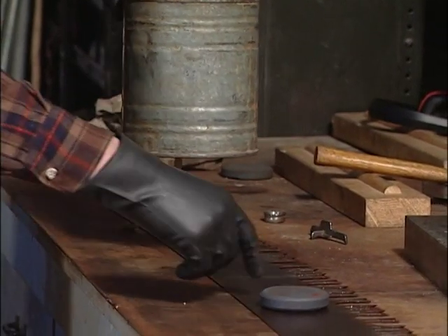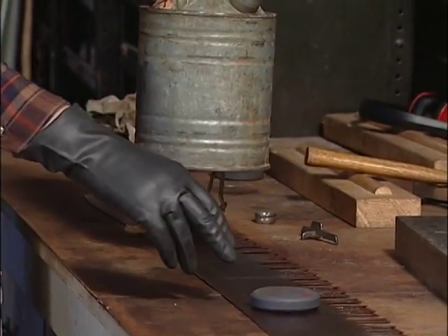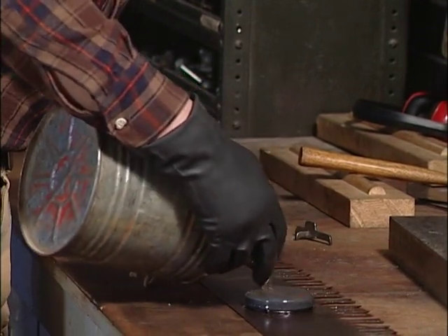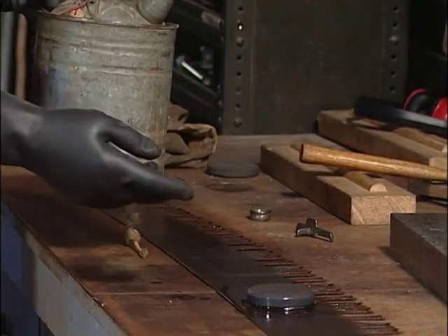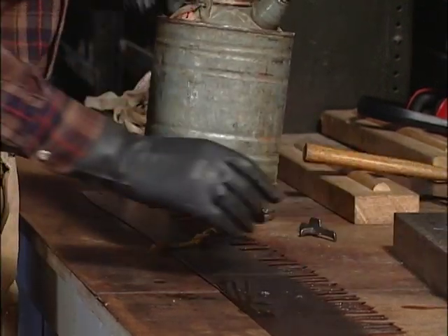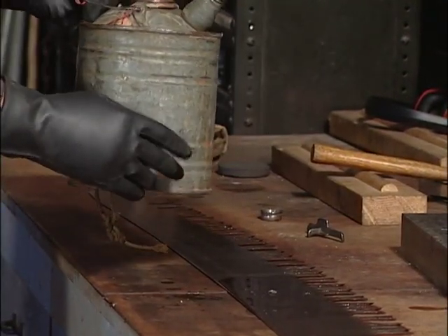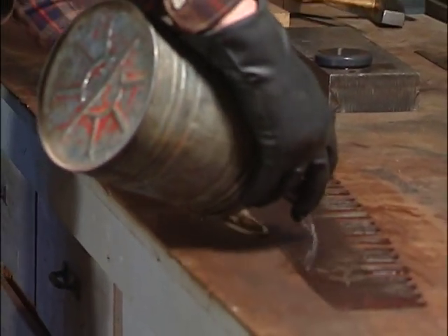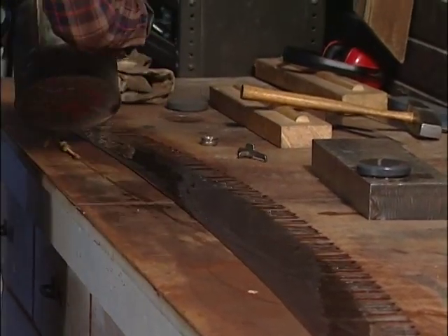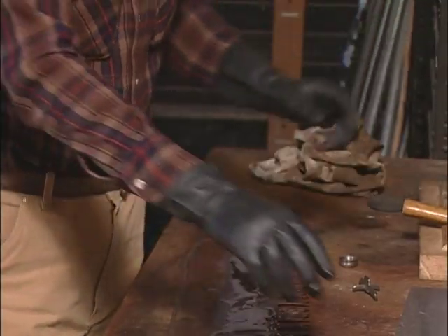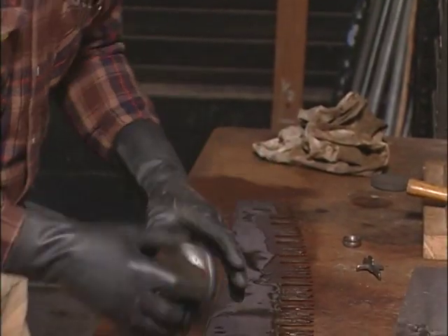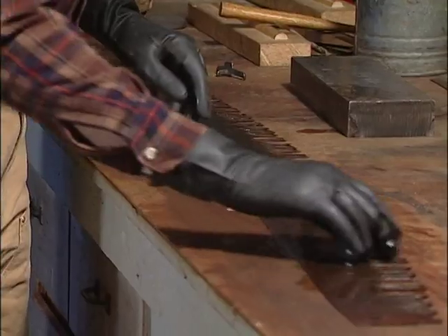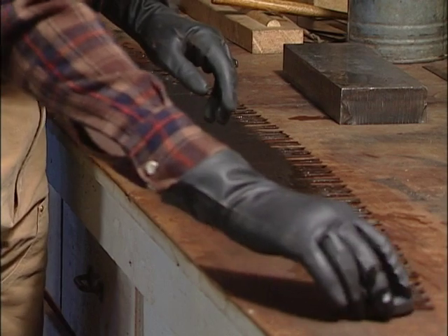Generally, with a stone that you haven't used before, it'll be pretty dry, and so it's a good idea to put a little bit of kerosene on the stone to get it soaking up. I can put the stone up here like this and let the kerosene soak into it. And then I'll just take kerosene and liberally douse the saw like that. And with the stone, I just spread the kerosene around so that it will start softening any pitch that might be on there.